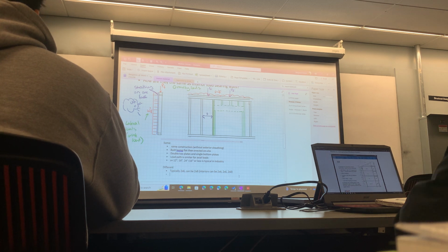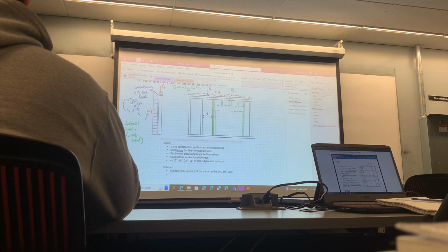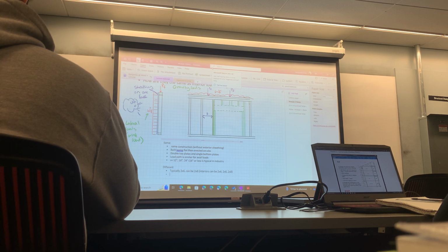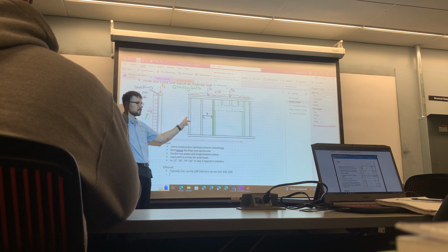How long? Very little. Instead of thickening the walls, who did building science? Have you guys done building science? What happens when you put more insulation between the studs? You get diminishing returns. Why? It costs more money for the insulation, but you're usually trying to put more insulation in to get a higher R value. The wood still provides a thermal path. Exactly. The studs are a thermal bridge, right?